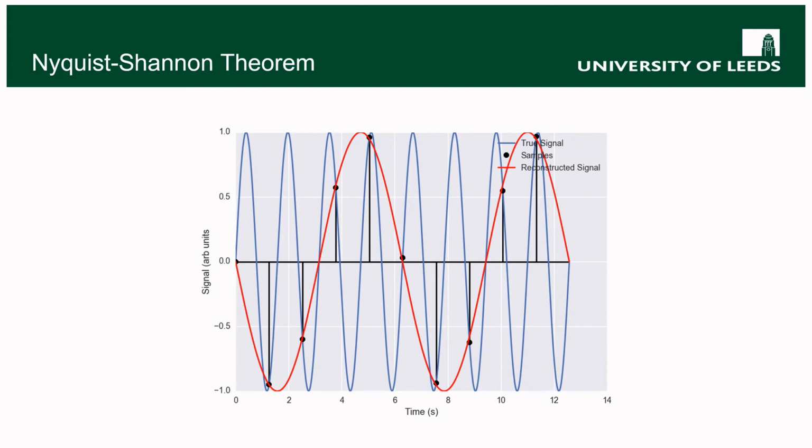And then you can understand why we need to sample at twice the frequency that you want to measure, because the beat frequency is the difference between the frequency you're interested in and the frequency at which you're really sampling it. So the aliasing signal means that as the frequency we're sampling at gets closer and closer to the frequency that we're trying to measure, we get closer and closer to looking at the red curve, which is actually going to measure just a flat line.